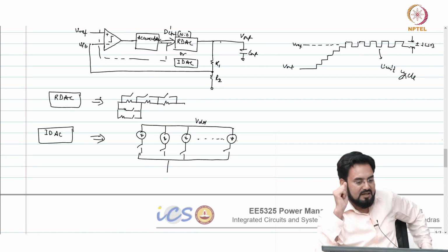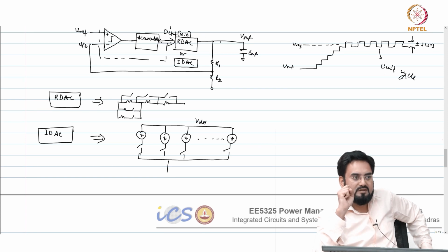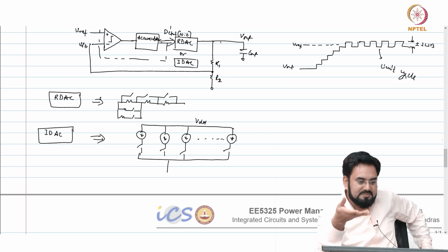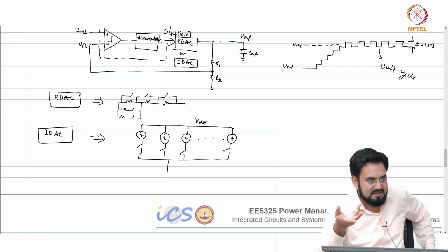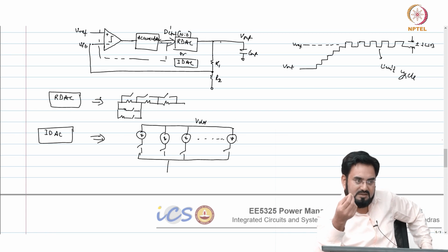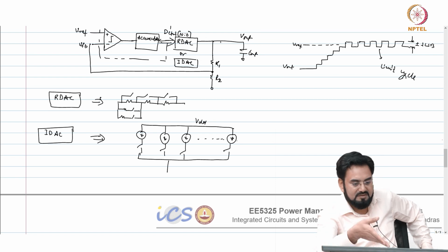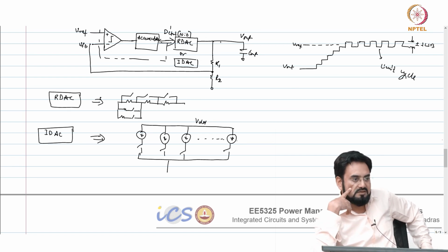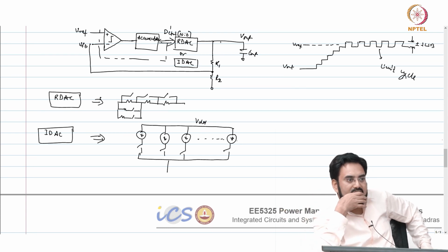Similarly, if you add a higher value resistor or remove the higher value resistor, it will change the current by a smaller value. Okay. So, your LSB, the accuracy, will be decided by the highest value resistor you are choosing, that will define your LSB size, because that will cause a minimum change in the current. So, then you have to decide what will be the resistor based on your lightest load. When you go to the highest load, that resolution will further improve. Okay.